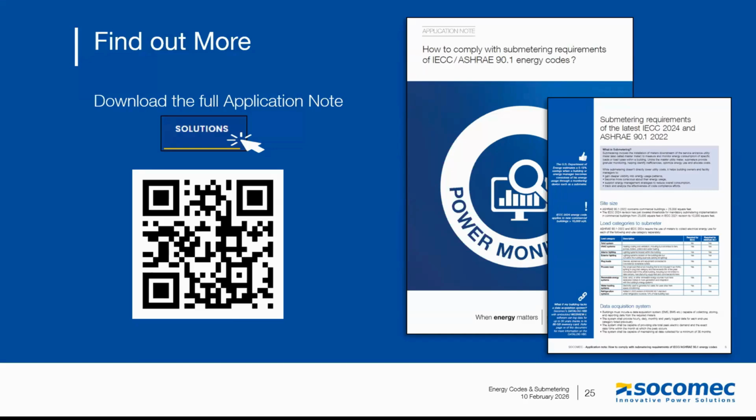They want to know how loaded the breaker is, what the load level is, because they want to make sure the breaker doesn't trip. So they want to make sure each breaker stays below 40%, for example, so that they know they can't add more servers to the rack. It's really a different application than what I presented today with energy code compliance.